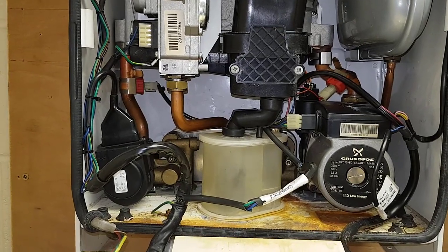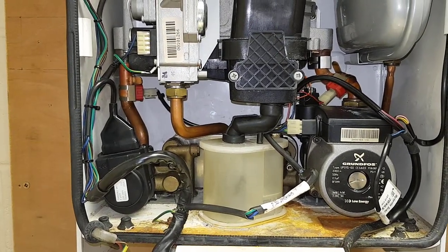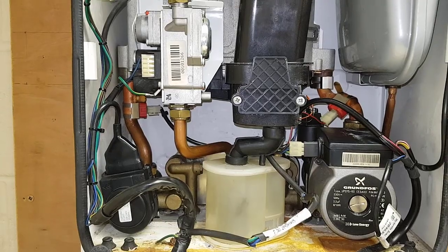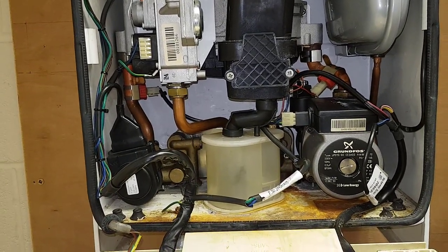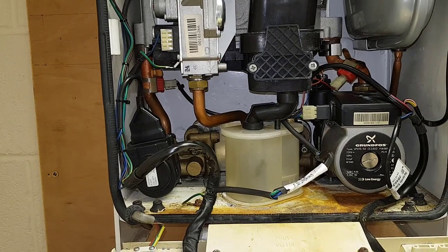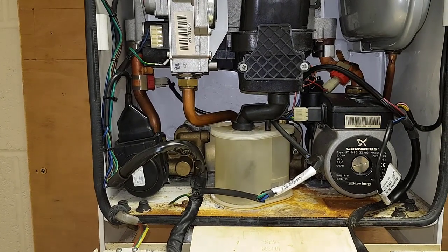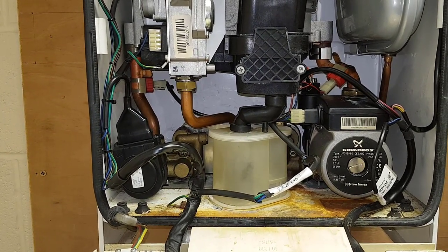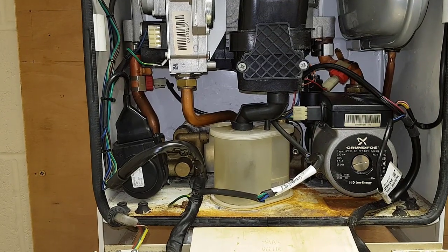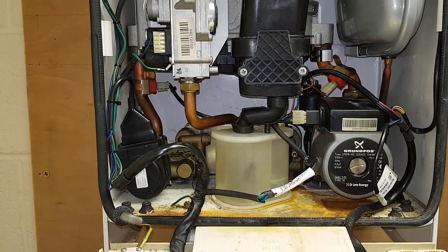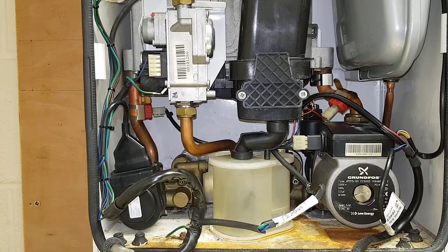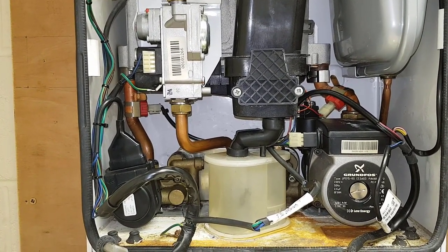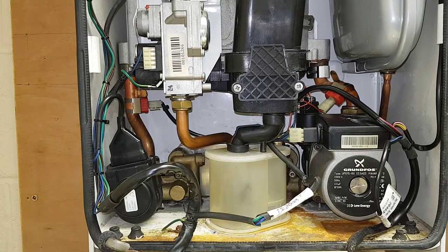All right, so on the next quadrant, what's that one? That's ignition failure. Right, so let's just run through quickly what the possibilities are. On that, we'll check if the condensate is blocked, if the gas valve is blocked or faulty, if there's gas supply coming in, and if the injector is blocked.